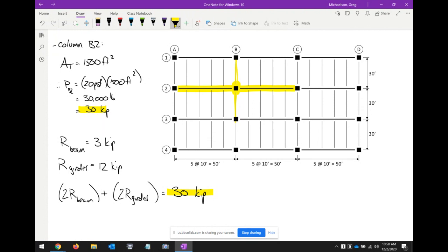Like, these loads can get amped up real quick, you know, and think 20 pounds per square foot didn't even show up on that table on the slide, right? We were talking about hallways with 100 pounds per square foot. We were talking about libraries with 150. The loads in structural engineering land get real high real quick. So it gives you a little bit of an understanding of the bigger picture, because if we screw up, that's a lot of force that can cause a lot of damage. But I just think this is kind of slick how in the end it all balances out, depending upon how you look at it. Any questions before we call it?